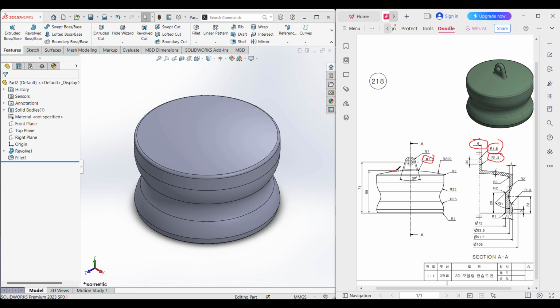We will not close the shape along this line. We'll take an offset of something like 1 or 2 unit extra, because this surface is not smooth, it is circular in profile. So if I take the dimension along this line, I cannot give this fillet of 1.5 unit because it will not connect the overall face of this upper circular face. That's why I will take a deeper line of offset to extrude boss this line. Okay, I will show you. So let's go back to our SolidWorks.